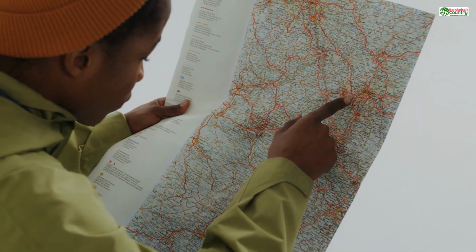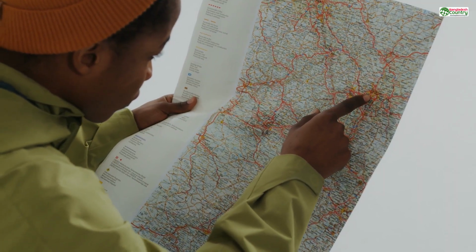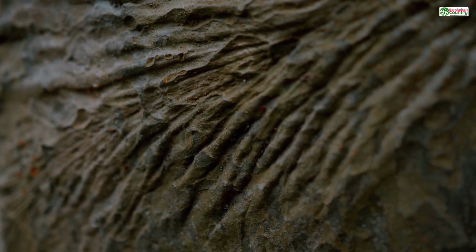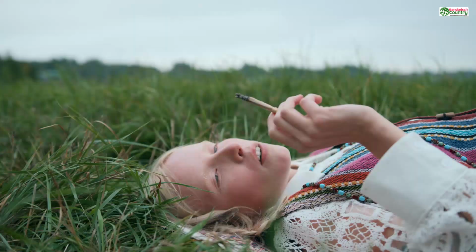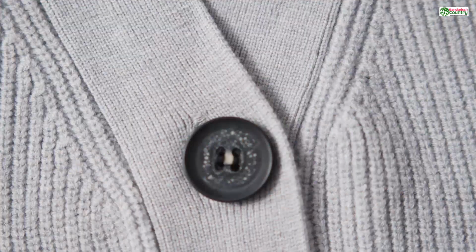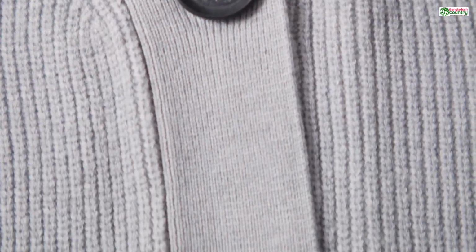Can you sacrifice the surface quality of a less important face by orienting it downwards to avoid supports on a more critical, visible face? For example, if you're printing a small statue, laying it on its back might eliminate the need for supports on the detailed face and arms, but it would create a flat, less detailed surface on the back. Is that a trade-off you're willing to make?